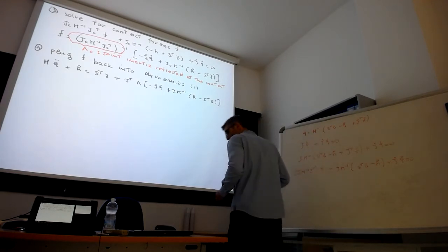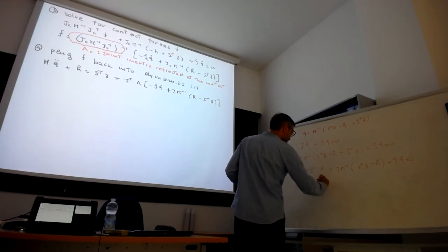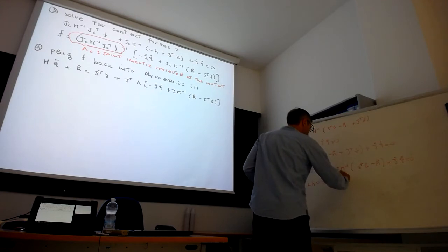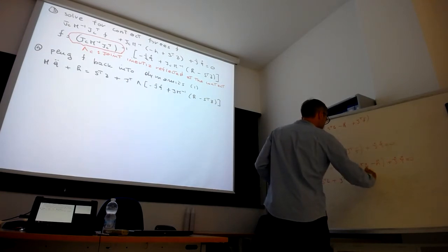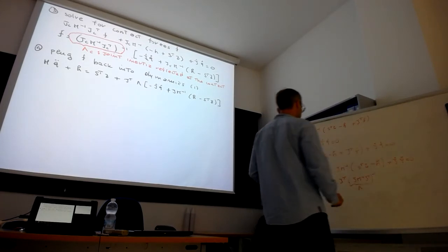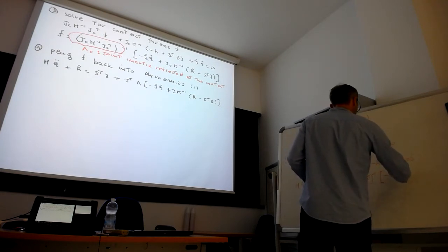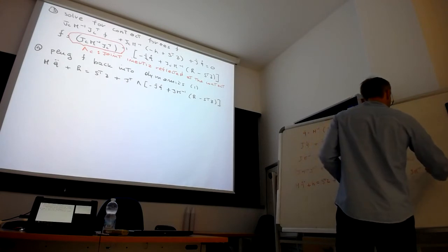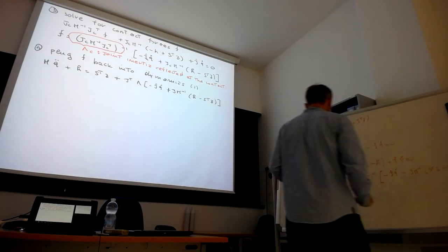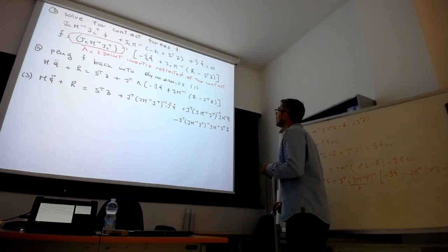So if we put the contact forces there, plus h equal to S transpose tau plus J transpose. This goes to the right, so f is J M minus 1 J transpose minus 1. This we call lambda, which is the operational space inertia. And we have this on the other side, so minus J dot q dot minus J M minus 1 S transpose tau times h.